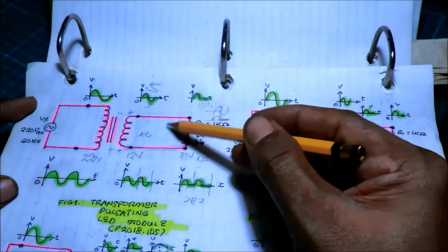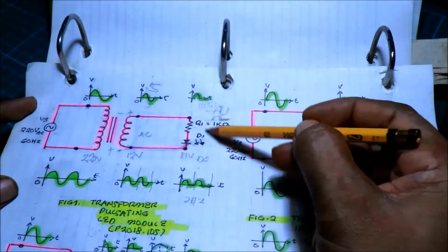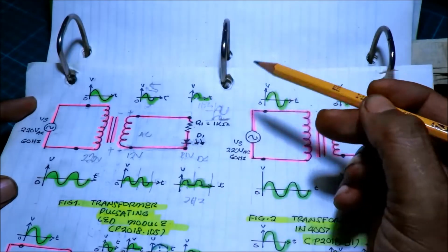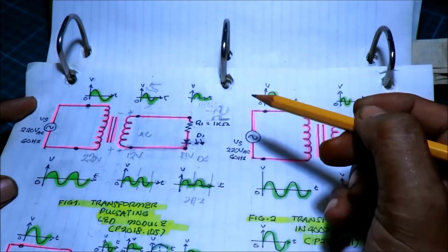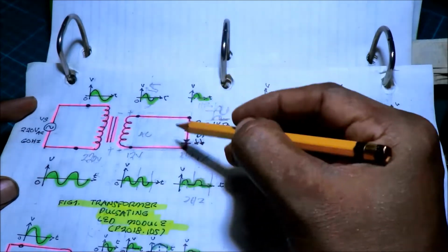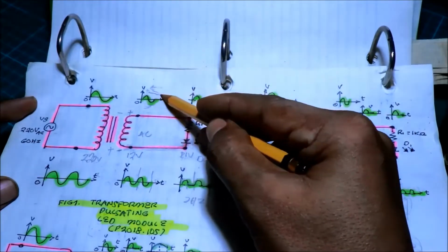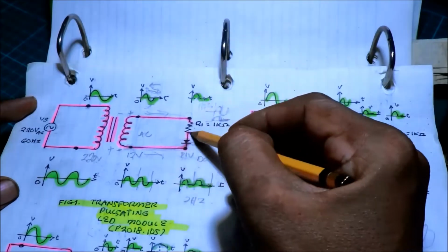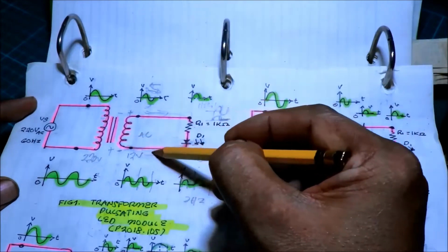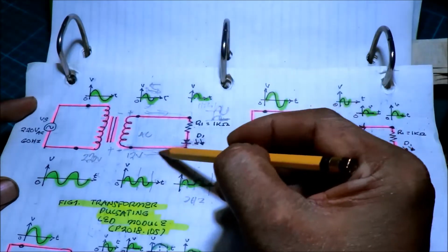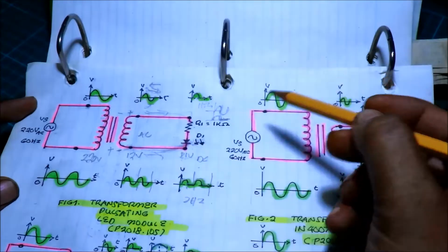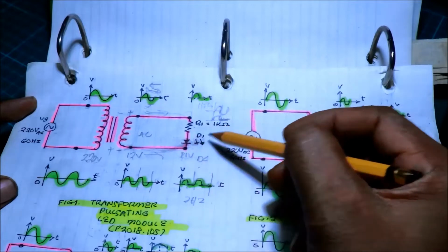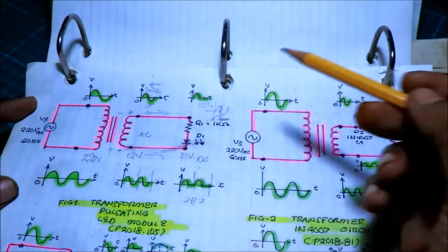That is the disadvantage of this circuit. But still, you can connect this for at least a short period of time, but not for a very long time, because the wave is traveling alternately from here and here. Half cycle travels here, the other half cycle travels there, and there comes a time this will burn out because of the low PIV of the LED.